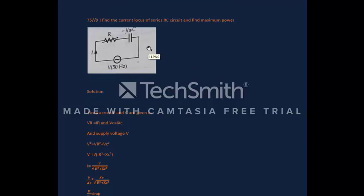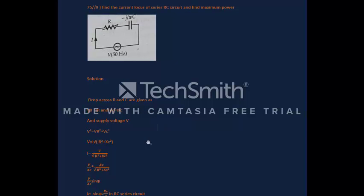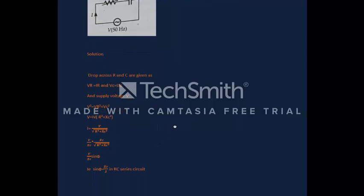So now let's go to the next question. In this question we need to find the current locus of a series RC circuit, and find the maximum power. So let's see the solution. This is the circuit diagram. We'll find the drop across the resistor and capacitor, given as VR is equal to IR and VC is equal to I into capacitive reactance.